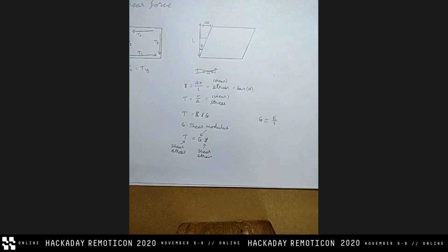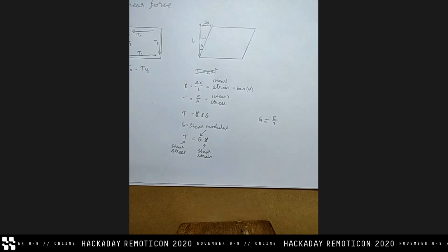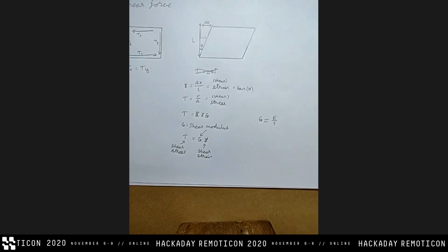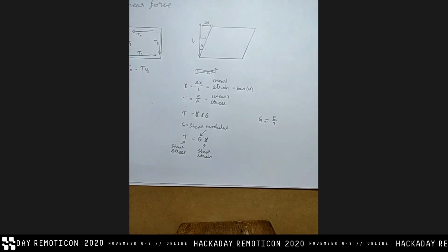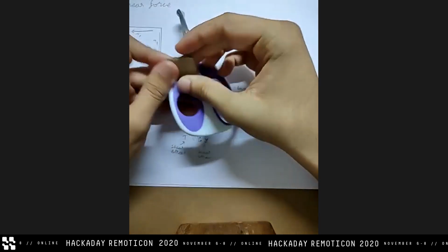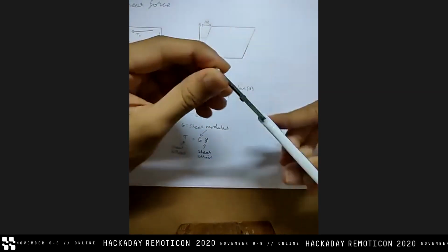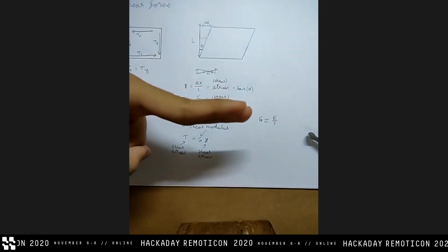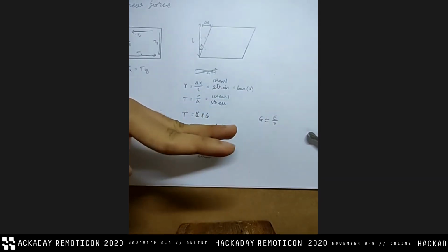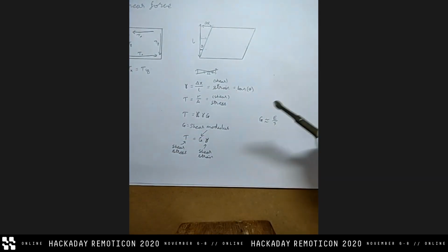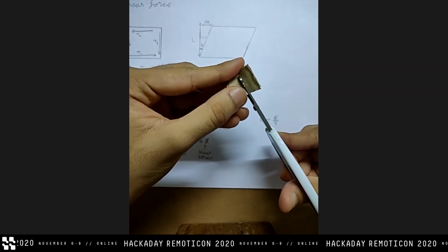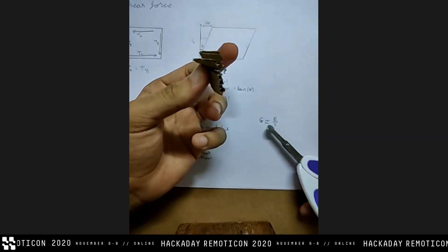And now the final and probably the most cliche example of these forces is scissors. Let me just grab this sheet. With scissors, if you see, these faces aren't actually aligned. If I do a diagram of scissors, it's not like this, it's actually like this, where they're offset from each other. And that is why they're able to shear it, because they make the area very, very small, and that's what allows scissors to cut so effectively.